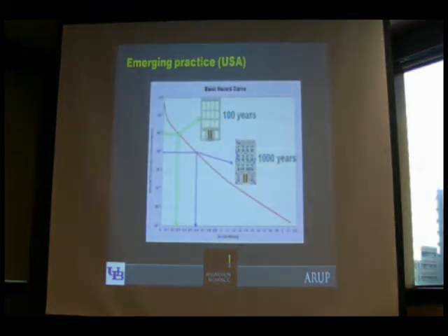Now, with performance-based earthquake engineering, the Generation 1 tools, we seek to match performance level and hazard level. We do this explicitly. If you think back to the discussion on the CTBUH Blue Book, we said we don't want damage in a frequent earthquake. And whilst damage is fairly easy to understand, frequent wasn't defined. When we talked about life safety in a rare earthquake, well, there are probably 60-odd folks in the room, and I could ask each of you to define life safety, and I'm sure I'd, at the end of the day, have 70 answers. And also rare earthquake shaking wasn't defined.